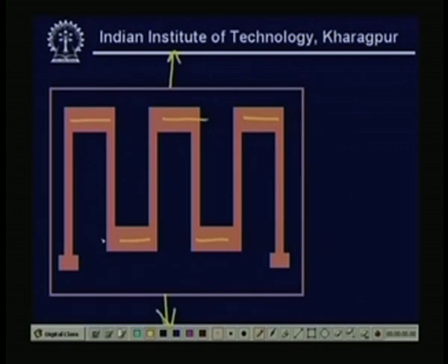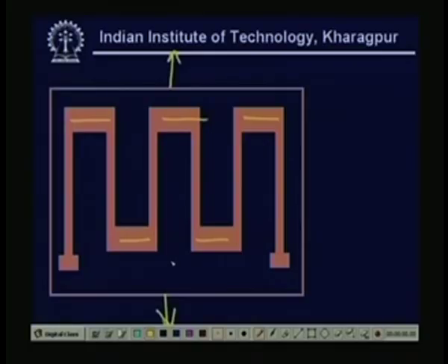But while I am making the calculations, I have not included this part. So, what do I have to do? I have to make it thick, so that the value of R in these portions will be very, very small compared to this portion. So, the contribution to the transverse strain, or the transverse strain error, in this case will be very, very low. That is the reason for the metal foil gauge, because in the case of a wire gauge I cannot change the dimension of the wire in between, but in the case of a metal foil gauge we can do it, because the principle of the printed circuit board is utilized to make this type of gauge.